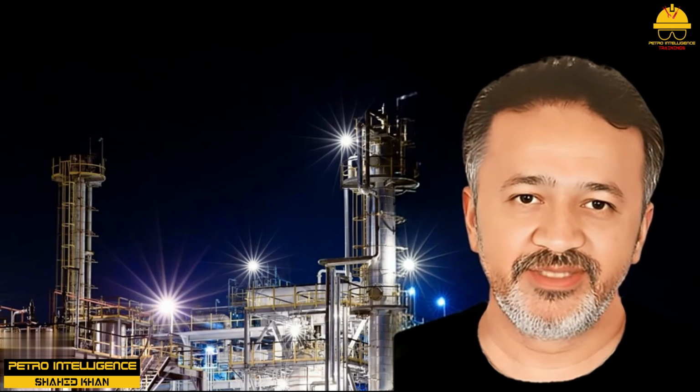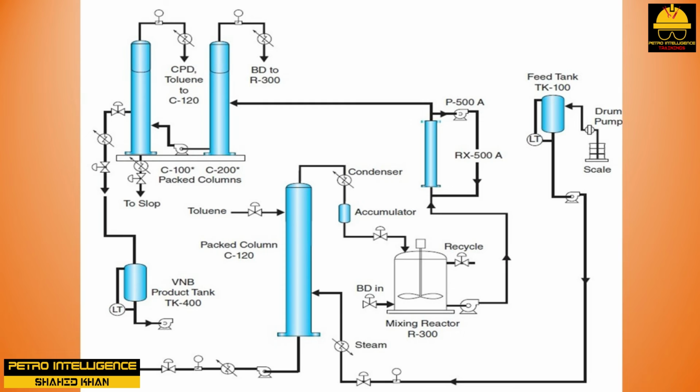Chemical synthesis. The purpose of the tubular reactor in chemical synthesis is to combine cyclopentadiene, CPD, and butadiene, BD, to form, synthesize, vinylnorbornene, VNB. VNB is the primary component added to a sodium catalyst and alumina to make ethylnorbornene, ENB, a special additive used to strengthen common rubber products.